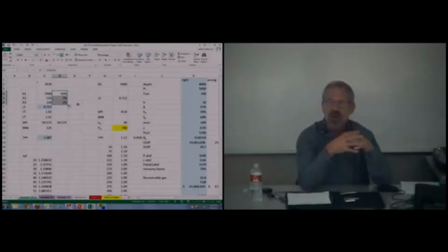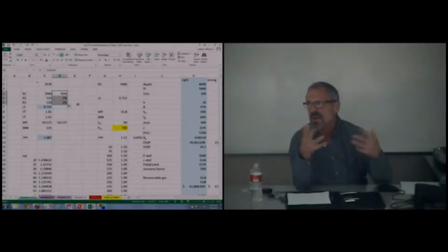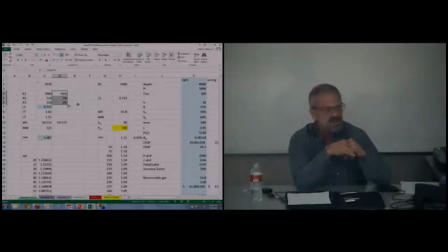Gotcha. But just on an MCF basis, 92% of the gas is coming from the primary separator. That's why we never had the numbers on the other two, especially that last one, 2%. That's why it's usually vented. Not anymore, because we got more health and safety regulations going on. Our industry is wrapping up that 2% these days.